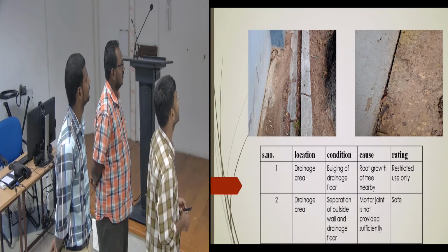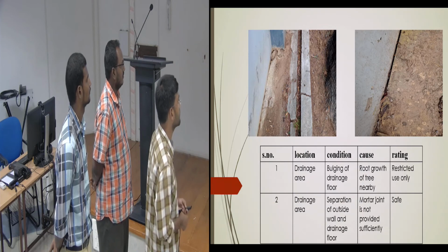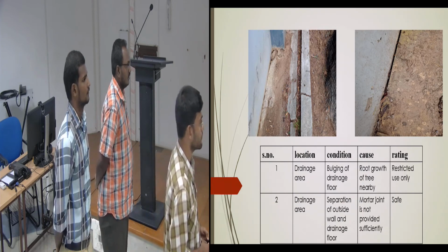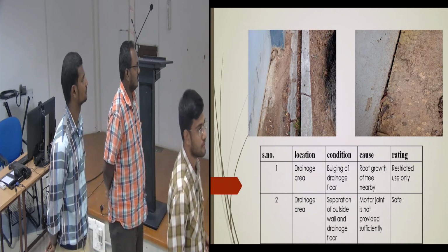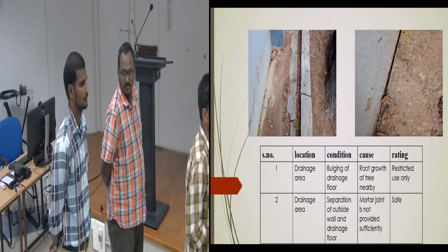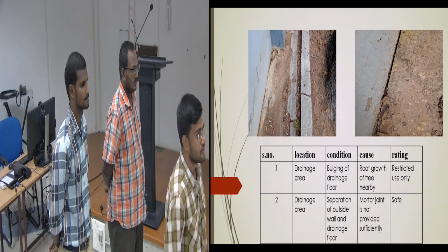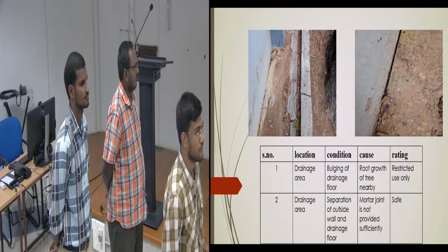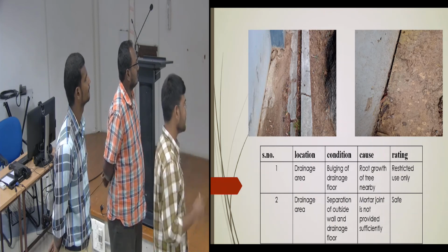Otherwise, what will happen? Your columns and these portions will still widen. It will crack due to the stagnation of drain water, which was not functional. Because of alternate sunlight, dry and wet, it will cause some issues. It will not be because of settlement, but because of this seepage action, which takes a long term, and that's why you can see some evidence again here.